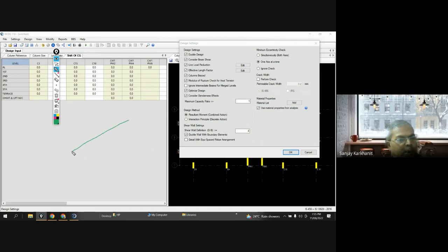See, if you are having a shear wall, something like this, this may be, let's say, 2000, the length or you can say depth of the column, and this may be say 250, or let's say 300. So now you can see 2000 divided by 300 will definitely be more than 4. I am not going to calculate. So it will consider this vertical element as a shear wall, and it will apply all codal provisions regarding shear wall.